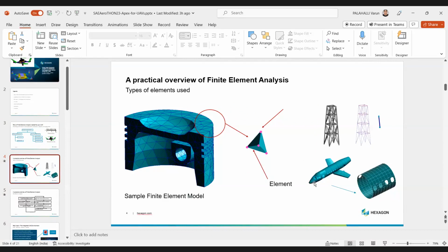So these are what are known as your 2D meshes or 2D element properties. What happens here is that essentially these do not have a thickness. Can you see? It is just a thin walled body. It is of zero thickness. So the structure has X and Y. You can say that X direction, Y direction, like it's like a plate essentially, and nothing in the Z direction. However, the Z direction thickness is specified by mathematically providing a thickness.